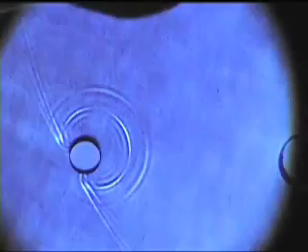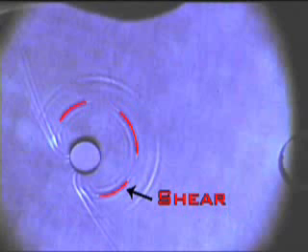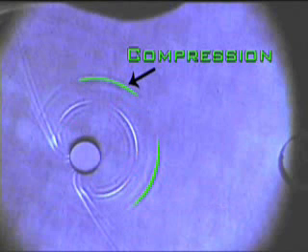But at any angle away from the perpendicular, an incident shear wave at a solid to free boundary interface will mode convert, and, in addition to the reflected shear wave, a reflected compression wave occurs. The compression wave moves off in a similar cylindrical shape, but at about twice the shear velocity. The associated wavelength of the two modes, as well as their positions in time and distance from the target, can be used to verify the modes.